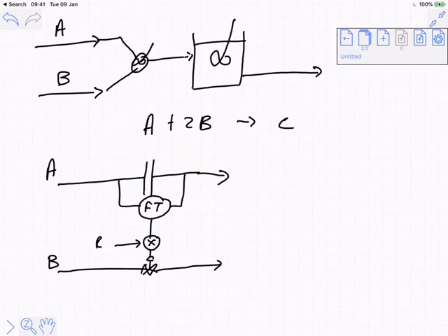So what we're basically doing, and you can draw this a couple of ways, you can draw a version of this which is even simpler, where that ratio is actually just implemented by a multiplication factor, which is built into a gain unit, right? So you can imagine, I've drawn it here in such a way that it implies there may be a knob somewhere that you could turn to set the ratio. But obviously you could conceivably just build a thing that takes that signal, multiplies it by 5 and writes it down to the valve.